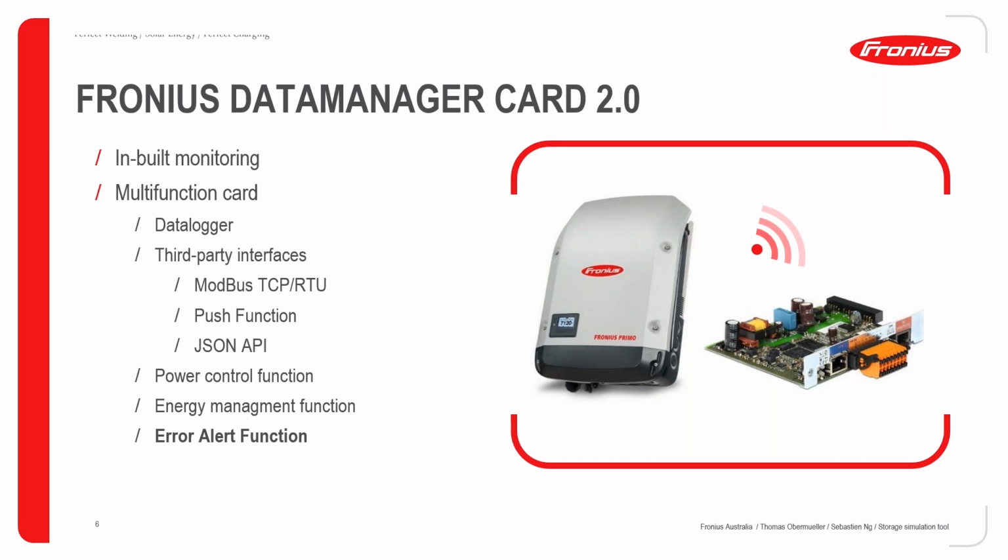But we can also talk to third-party servers, for example with the push function. So there are a lot of capabilities within this card. We can also do power control functions, which means if you need to do export limiting, or if you need to ramp the inverter up and down, you can do it via this card, and of course energy management functions, so turning different devices on and off.